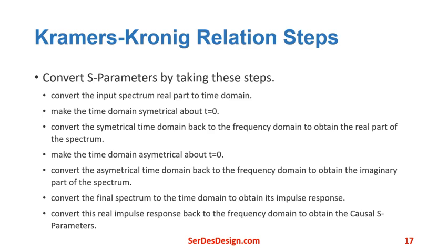The Kramers-Kronig relation steps that I use. The S-parameters can be made causal by use of the Kramers-Kronig relations by taking these steps. Convert the input spectrum real part to the time domain. Make the time domain symmetrical about t equals 0.